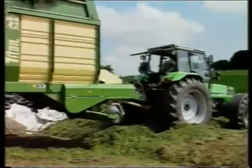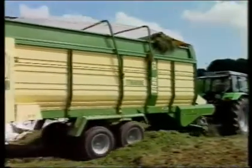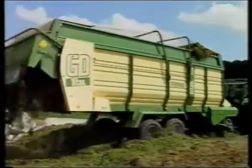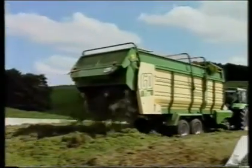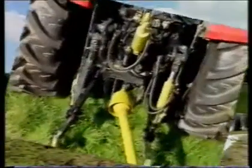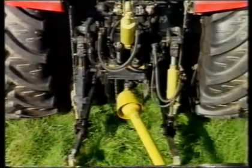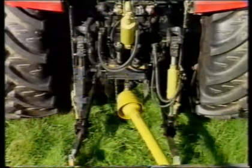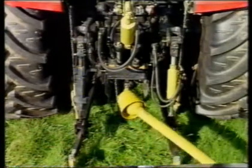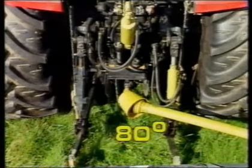The maximum bending moments, MB1 for the rotary angle position 0 degrees and 180 degrees, as well as MB2 for the rotary angle position 90 degrees and 270 degrees, are calculated from the incoming torque, M1, and the joint working angle, alpha. Mastering these theoretical principles is the prerequisite for precise and practical design of a complete driveline system, in which all drive components are matched to one another.